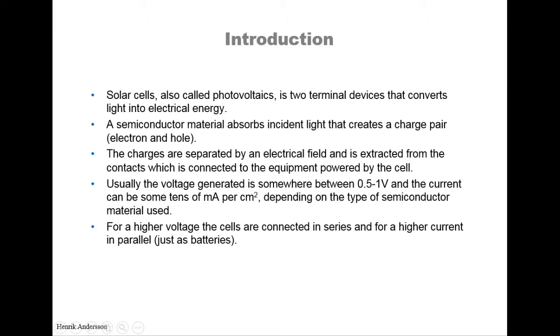Solar cells, also called photovoltaics, are two terminal devices that convert light into electrical energy. The semiconductor material absorbs the incident light and creates a charge pair. The charges are then separated by an electrical field and extracted from the contacts connected to the equipment powered by the cell.